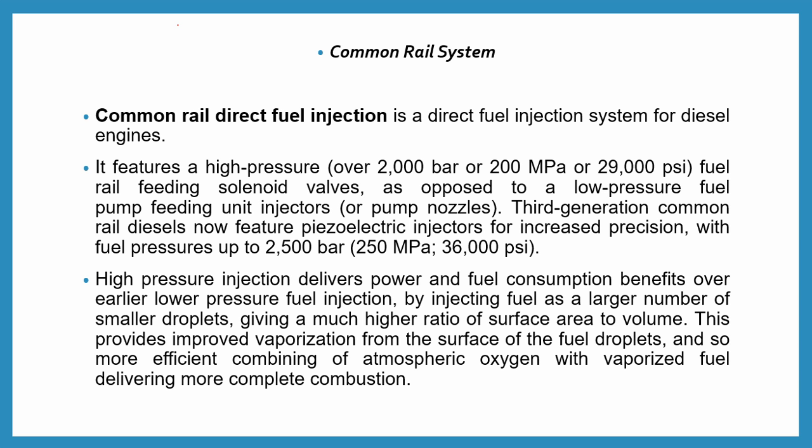This high pressure injection delivers power and fuel consumption benefits over the earlier lower pressure fuel injection. By injecting the fuel as a larger number of smaller droplets, it gives a much higher ratio of surface area to volume.